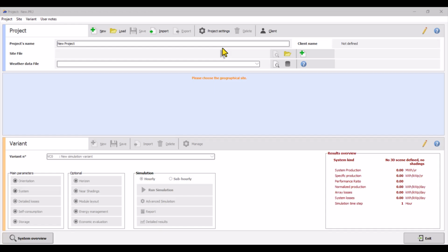In this tutorial, you will learn how to enable bifacial PV modeling when designing a dome-shaped solar PV system in PVsyst. By default, PVsyst does not allow bifaciality to be activated when a project is modeled using the dome-shaped orientation. This is because the dome-shaped orientation is a simplified array model intended for fast energy simulations and does not perform the detailed rear side irradiance calculations required for bifacial models.